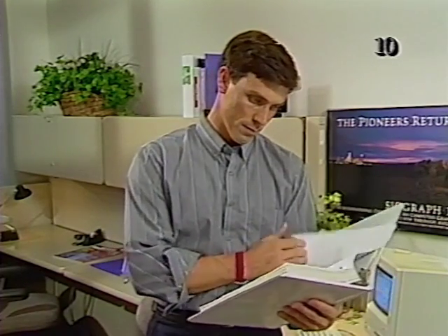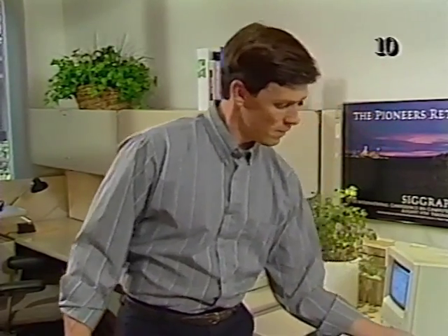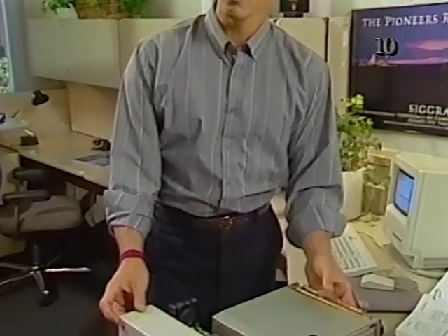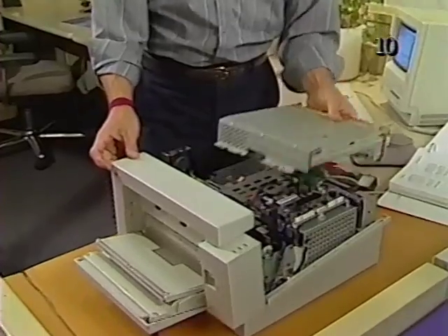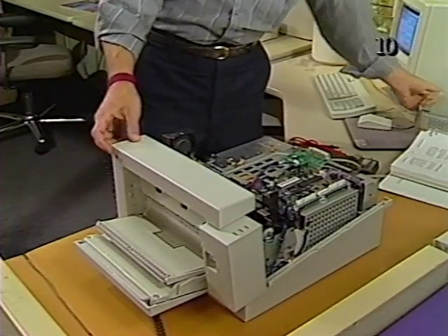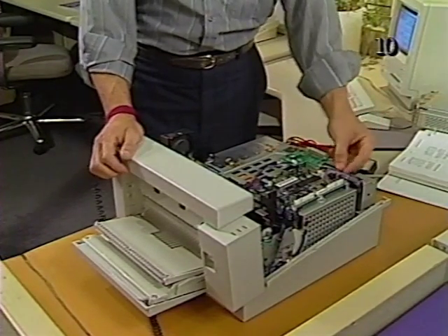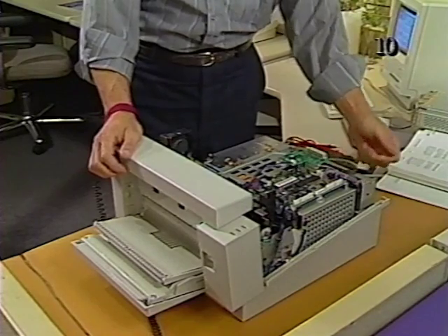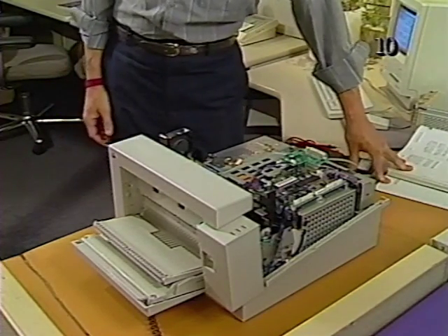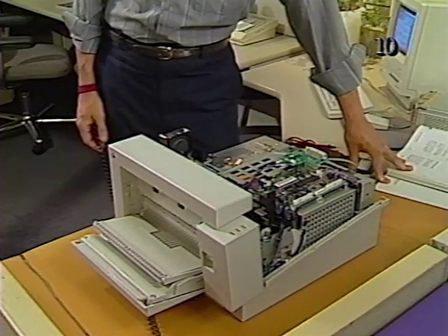Based on the print engine error flowchart, you should turn to troubleshooting Table G, laser scanner malfunction. After removing the I/O shield, check the optical fiber cable. The optical fiber cable is properly installed. What should you do next?